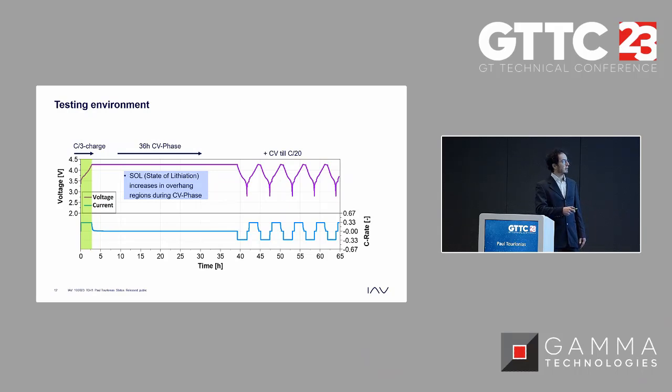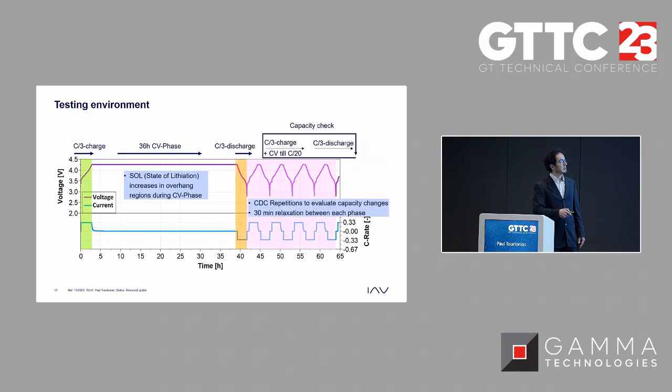And after that very long phase, we do some discharge and charge cycles with repetitions to evaluate the capacity changes over these successive patterns. Between them, we put some relaxation time of 30 minutes, which is shown there.